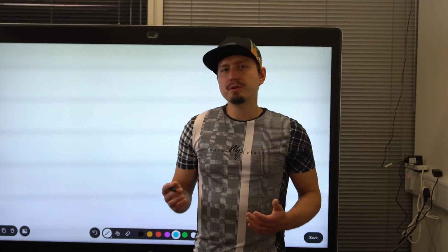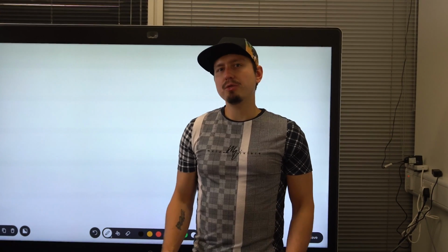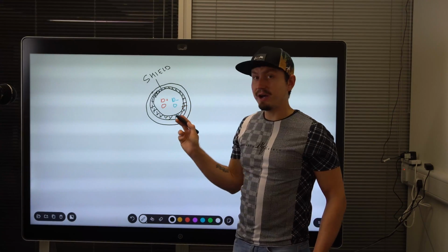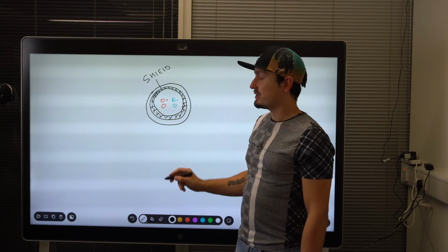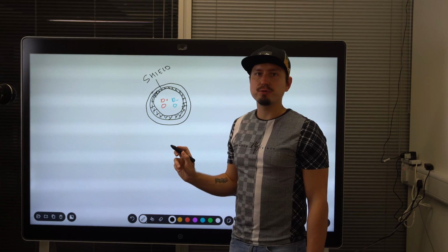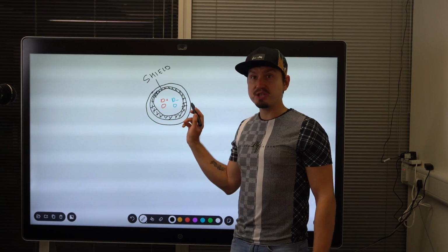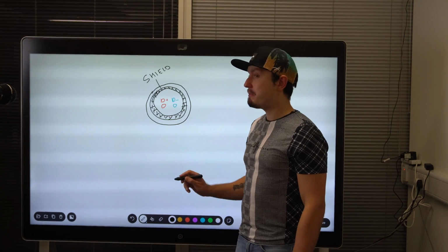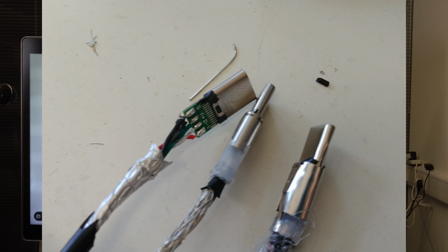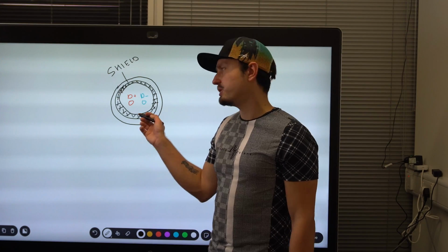I have made a video about that, and the majority of cables on the market are not 360 degrees shielded, and this causes a lot of issues when we ship this cable with the product. It should look something like that, where we have cable pairs inside the cable and a continuous 360 degrees shield around them. To check that this is true, I have not found a better way than to open up the cable and see for myself, and I have talked about this before.